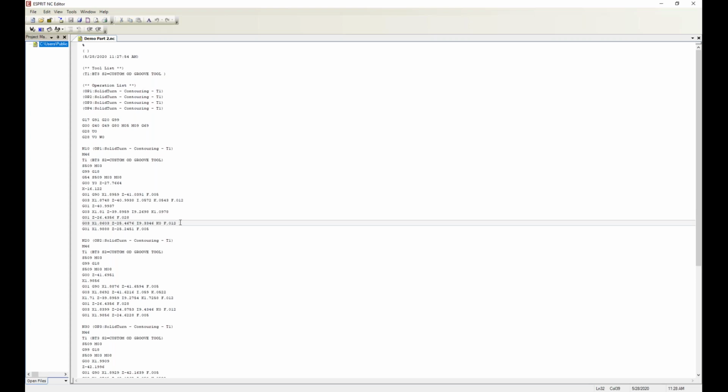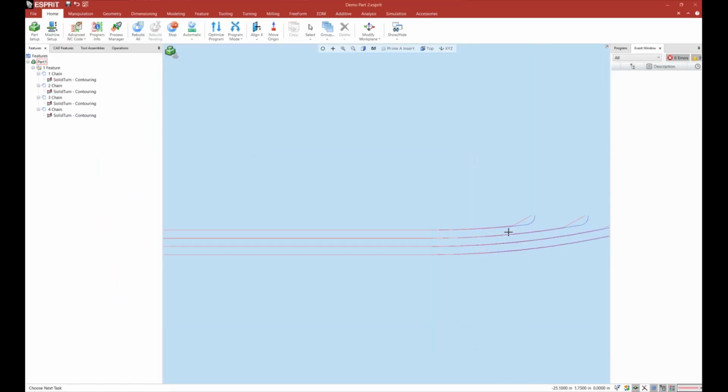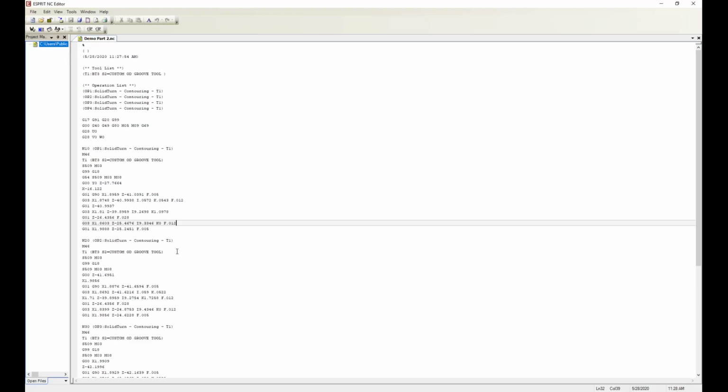And then I also had added previously the reduction in feed rate towards the end of the operation. So towards the end, when we're rolling out, you want to reduce that feed rate. And I already have the insert technology added there. And you can see then it reduces back down to that 12 thou per rev reduction, and then 5 thou. And so yeah, that's how prime turning is set up, and it is a really good tool to use within ESPRIT.